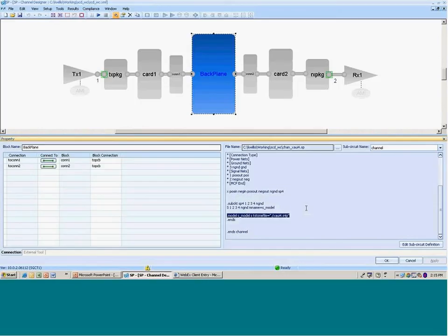So the fundamental approach here, from an ease of use standpoint, is to support basically whatever kind of models you have available. We want to be able to use them in the topology to build out that die-to-die path. So if you have encrypted transistor level HSPICE models, or you have behavioral SPICE models, or you want to point directly to an IBIS file, W elements and HSPICE syntax, subcircuits, Touchstone, BNP format, any of those formats, you can plop right into one of these topologies and use them.